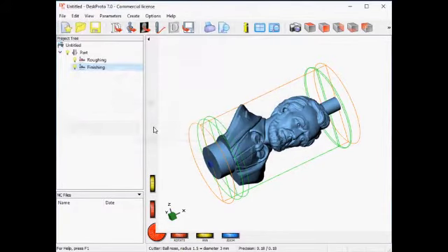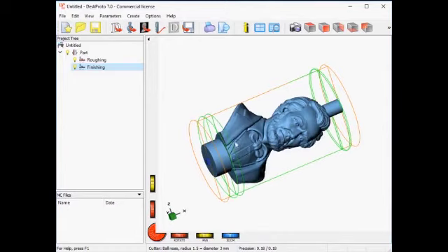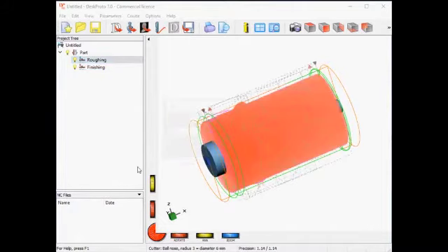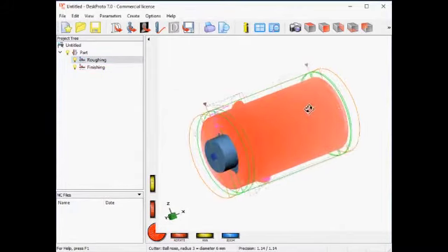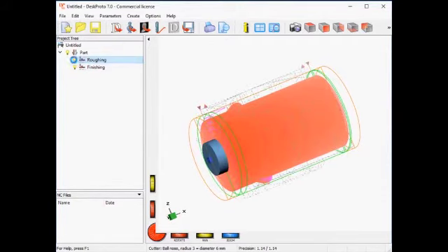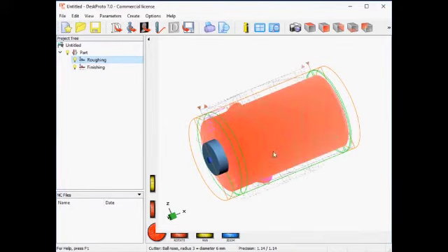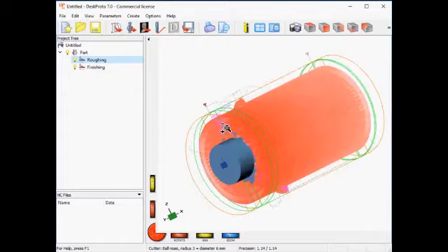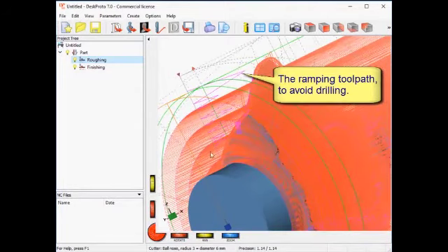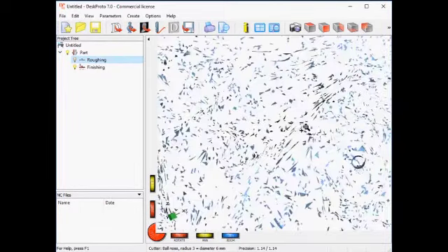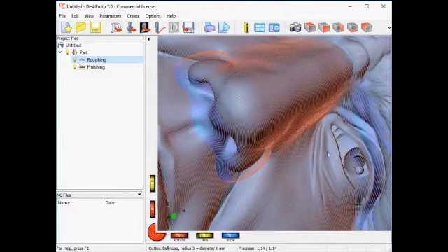Okay, here also okay. Now I've done all settings that I need, and I can start calculating the toolpath, which will take some time, so feel free to get yourself a coffee. And here we are, very many toolpaths. You can see the finishing, which closely follows the geometry, and the roughing, which goes down in a number of layers of 10mm each.